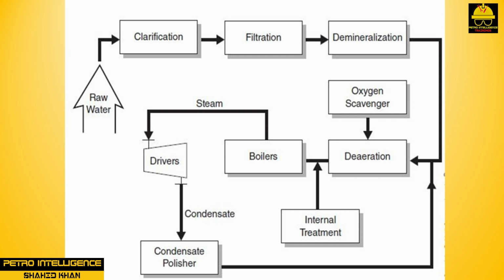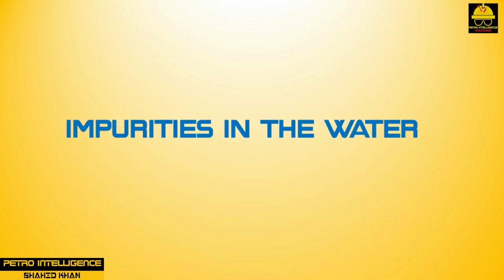The primary pump typically has 1 or 2 backup pumps that are placed in standby mode. It is essential that all impurities be removed, otherwise, harmful scales or excessive corrosion will occur in the boilers. High concentrations of dissolved solids in boiler water will cause foaming of the water within the boiler. Foaming produces carryover of impurities in the steam, resulting in deposits on the turbine wheels.